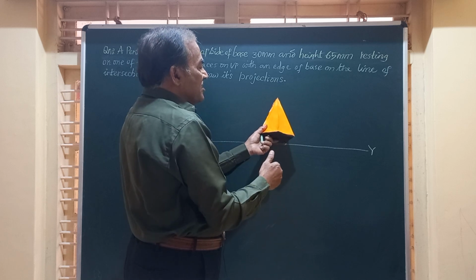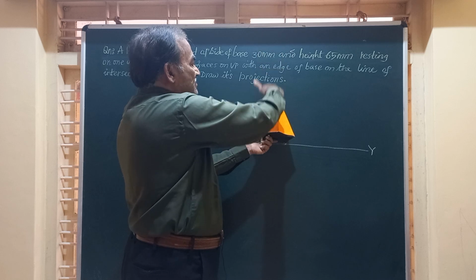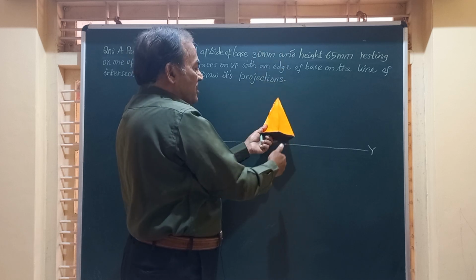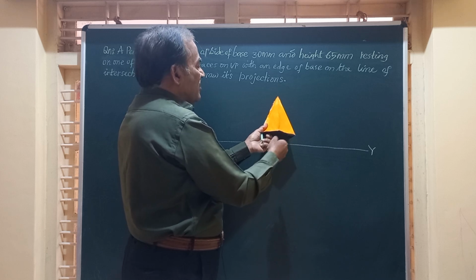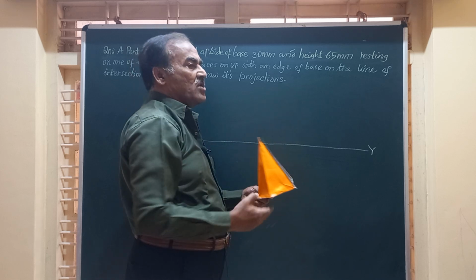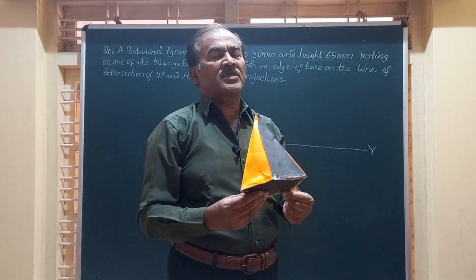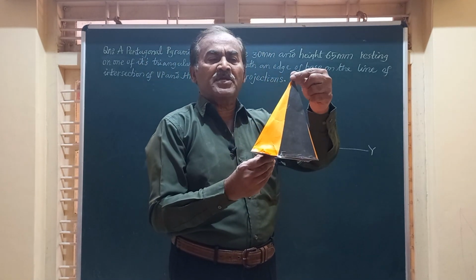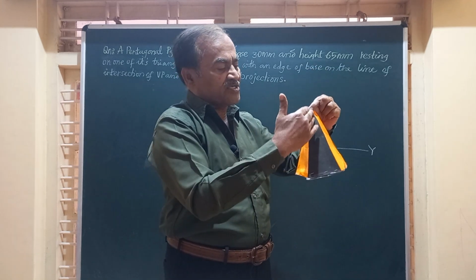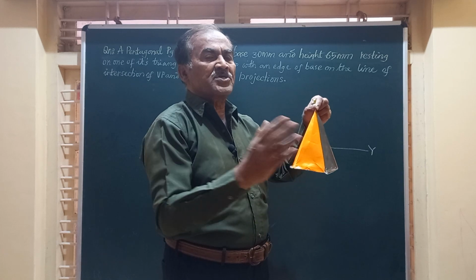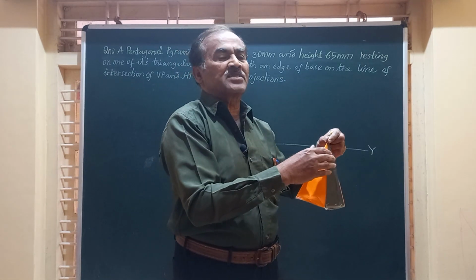And friends, you will be able to see the pentagonal base distorted in the top view. In the front view also you see the pentagonal face. To start with, it is very essential that we place the pyramid on HP such that this triangular face, which is going to rest on VP, should come to your right side in the top view.